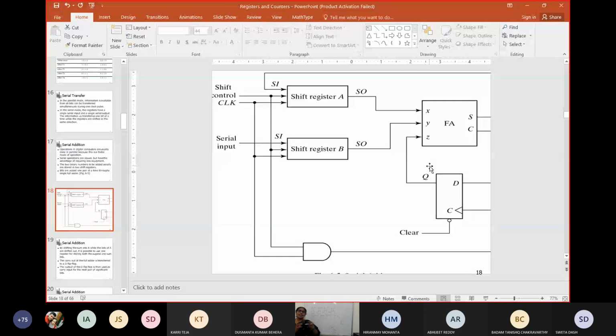So at that time it was halfway, half cooked. Now you can understand from where these are inputs, how the carry is forwarded, and how the clock is controlling the full concept. So this is just a full example of a binary parallel adder exactly worked out with the registers and clock pulse. So we cannot say a combinational circuit is different from sequential. Sequential operations are performed and combinational is a part of that. That time binary parallel adder was something different. And now you see, this is the actual binary parallel adder with timing, everything, isn't it?